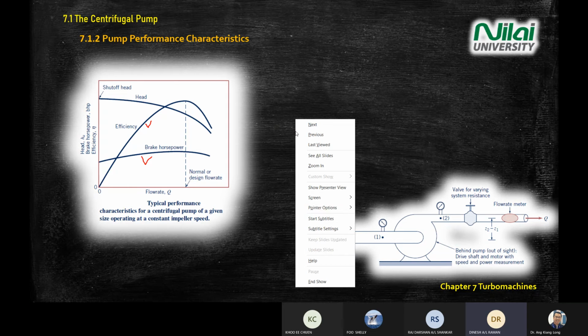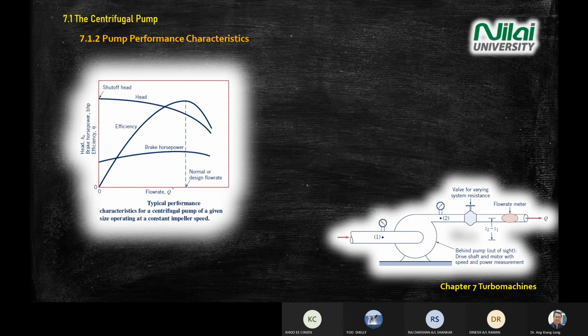Efficiency is the center one. Efficiency line, yeah. Okay, correct. So you're looking at the optimum value there. This is the most important line on the graph. Okay, then it will give you three related values. Once you get the efficiency, you get your Q, you get the brake horsepower value, you get the maximum head value, or the optimum head value, when you operate at this efficiency.